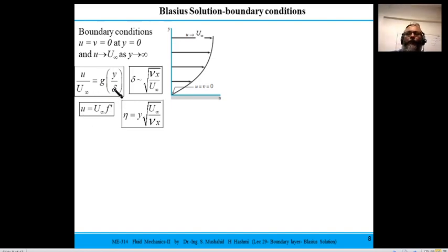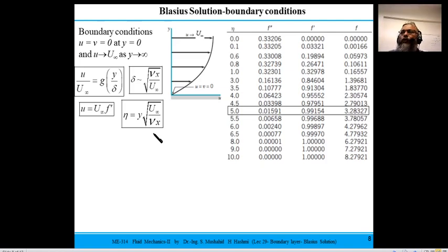We know that this dimensionless velocity is some function of y over delta, and we know there is an eta variable which is some function of y over delta, because the y is already there and this thing is the delta, or of the order of delta. So the solution looks like it is represented in this form, where eta is this variable and this is the function of that variable, and at that value of eta it is the first derivative and it is the second derivative.